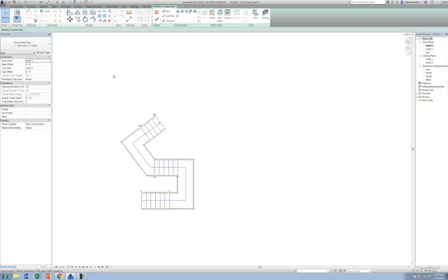The stair tool in Revit got updated a couple of years ago, and it's no longer sketch based. It allows you this kind of inferred customization. And we'll talk a little bit about how we can break that, take it back, and turn it into a sketch based tool to allow us to adjust it. In particular, today we'll be talking about the kind of stairs that you might be doing in a lobby, the sort of grand staircase that you might want to use as an entrance piece as you move in and through, especially the public parts of your project.